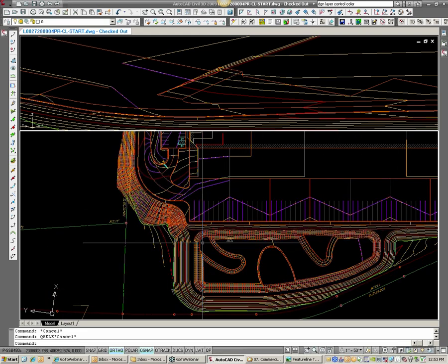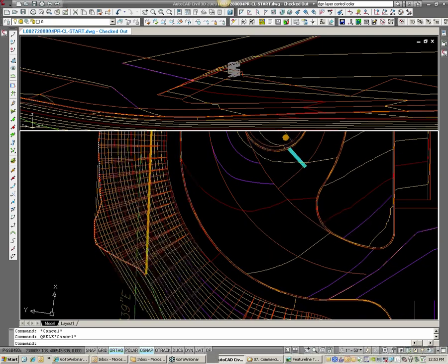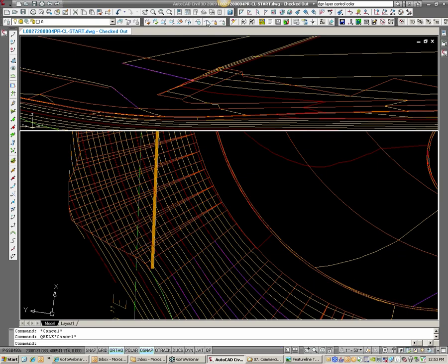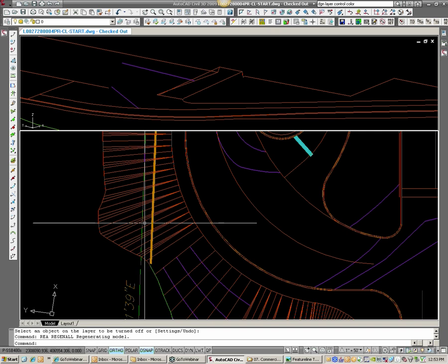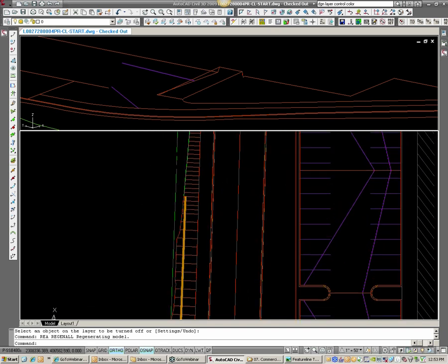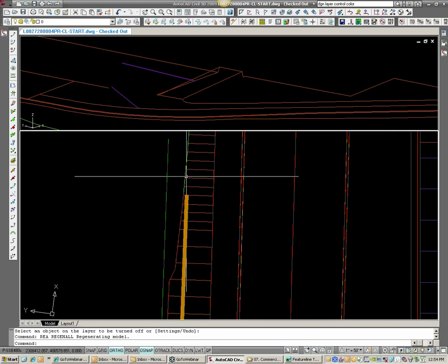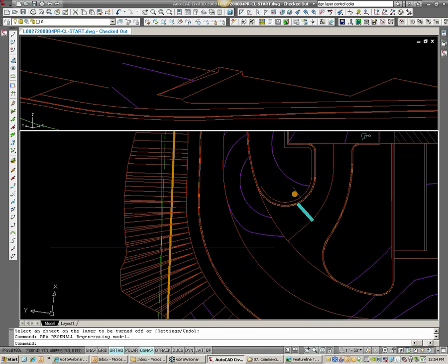Let's do the retaining wall here. Okay, so you have this site. This projected 2-to-1 slope goes out beyond your property line. So we need to do a retaining wall. So how do we figure out where we wanted that retaining wall to be? Let's turn some of this off just so you can see it. Well, we took the property line, which goes straight up through here. We offset it 5 foot back. Wanted to have at least 5 feet in between here for maintenance or whatnot. And then wherever that touches the daylight line at either end, that's where you know the retaining wall needs to start and go from there.